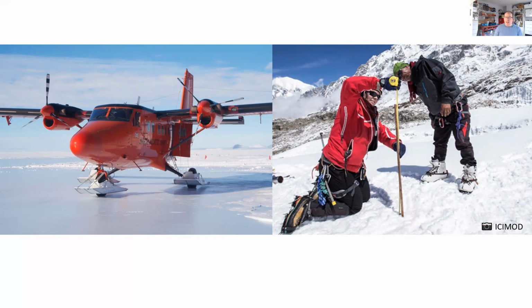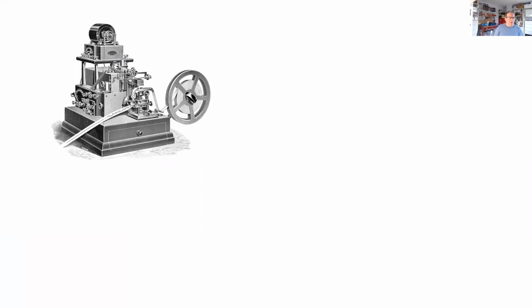And so I thought I would digress briefly into a history of some of the ways that we have automated things. So this rather lovely looking machine here on the slide is Lord Kelvin's siphon recorder from 1867, which, as far as I could tell from some fairly cursory research, is the first machine that takes in an electrical signal and makes a physical recording of it that can then be reviewed at your leisure. And this was actually intended for recording signals coming along long distance telegraph cables, like the early transatlantic telegraph cable. And it works by having a little tiny coil which is disturbed by the electrical signal and moves back and forth and directs a flow of ink, which comes out of a little needle-like nozzle onto a paper tape, which is then advanced by an electric motor. So it's the forerunner of both the data logger and the inkjet printer.